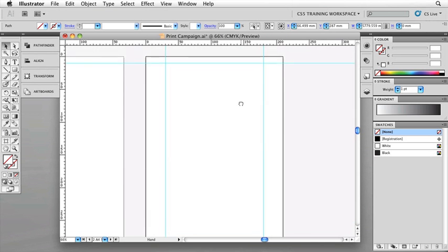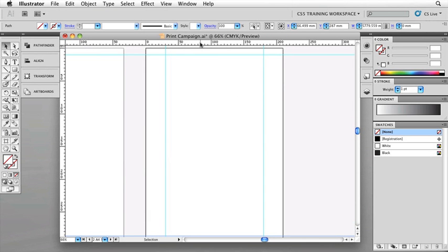Now likewise, let's do some from the top here. Let's click and drag and pull down into the page, and I'll use the Shift key here, and I'm going to drag down to 120 millimeters. So let's go down to here, that's 120. Once again, I can double check up here that my Y-axis tells me just that. Now again, I'm going to have another guide at 10 millimeters below this. In fact, I want two evenly spaced 10 millimeters apart below this.